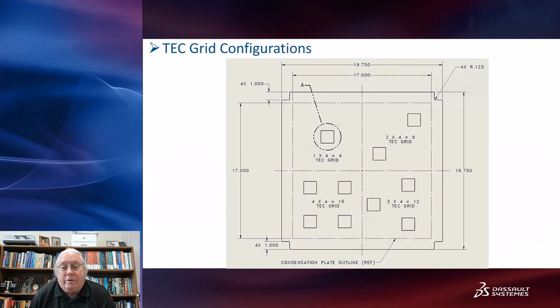So here's a picture looking from the front of what I call the hot plate. This is where the grids of these Peltier devices are. I have one of these, and these are 4 separate condensation plates. On the back side, it's one large hot plate. And on the near side, there's 4 condensation plates, so we can measure the temperature of these things.